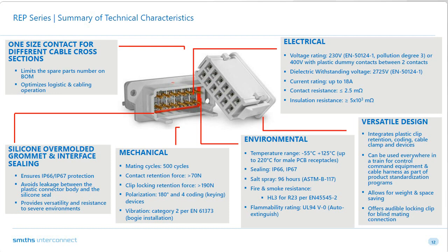In terms of mating cycles, it does over 500 mating cycles. It's got a very low retention force, contact retention force of greater than 70 Newton. The clip locking retention is 190 Newton. Polarization available and vibration up to category 2. From an environmental perspective, it can go as low as -55.